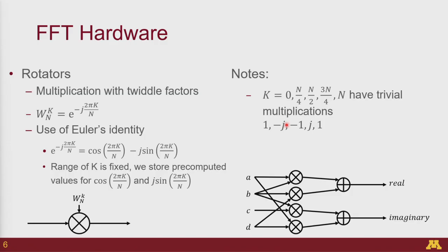all that implies is that you interchange the real and imaginary components while appropriately handling the sign, right? And similarly with a j operation. So whenever we see these kinds of multiplications within the DFG of the FFT, just know that these are not real multiplications, but trivial multiplications.